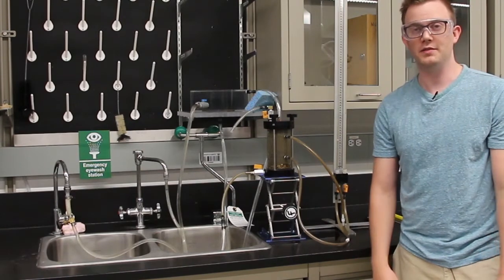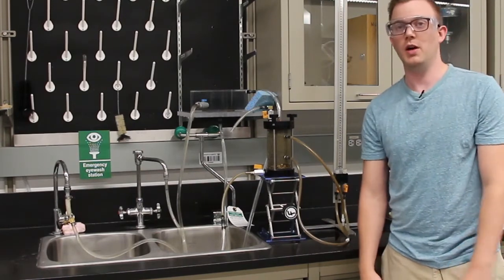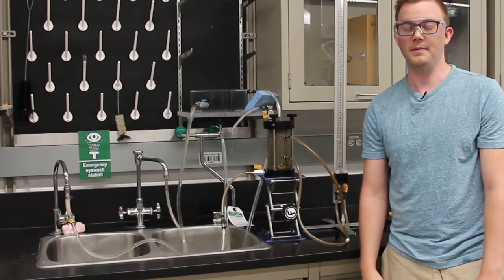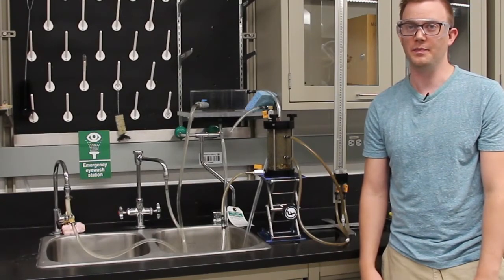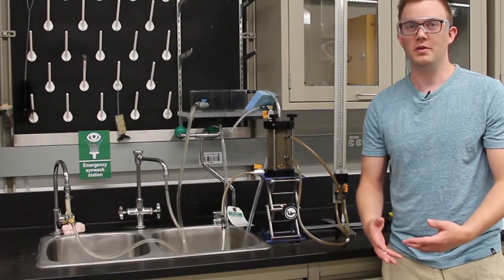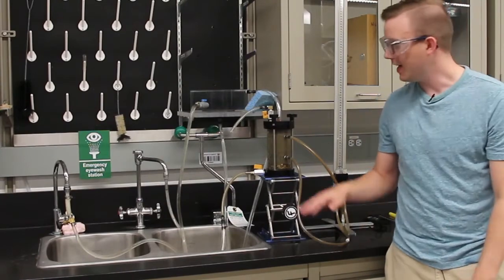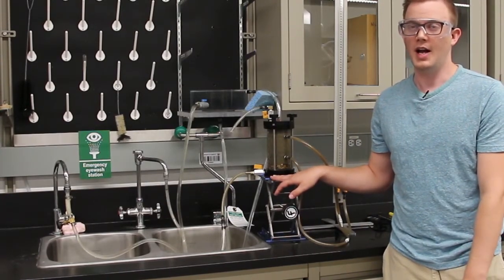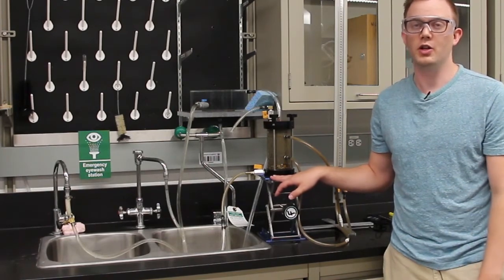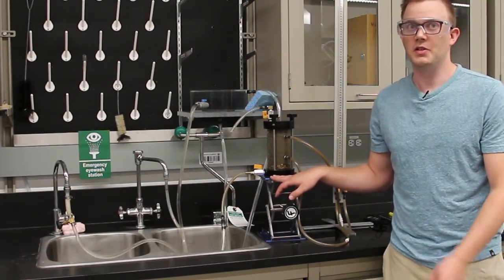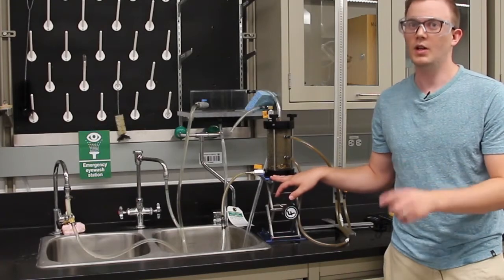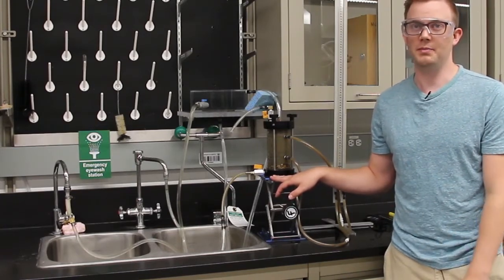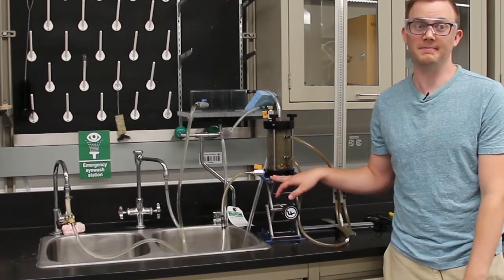Now, the other objective is we want to figure out at what gradient the sample is going to undergo the quick condition. So you should calculate at what height this should be to incur a gradient of 1. And then right around there is where your quick condition should happen. If it doesn't, just keep lowering your sample until that occurs. We'll give you a close-up right now on what that should look like.